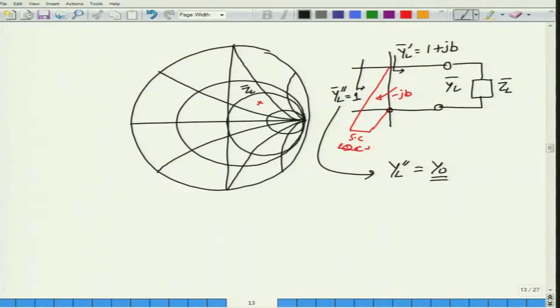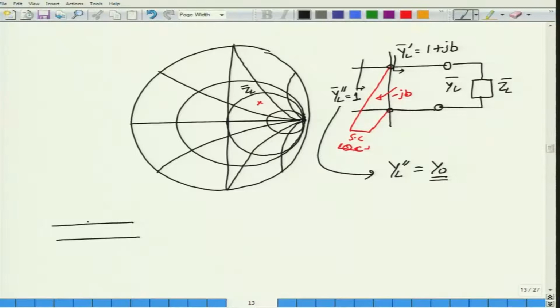You just have to take this point and connect a short stub, and you can do this very well even on a printed circuit board. So on a printed circuit board, let us say this is the track that is going around, then you can take a track and create a via of an appropriate length, or create a track of an appropriate length, and then do this. Of course, in a PCB, since you are not doing it in the dynamic case, you can even do the series stub, but consider an antenna tuner, for example.